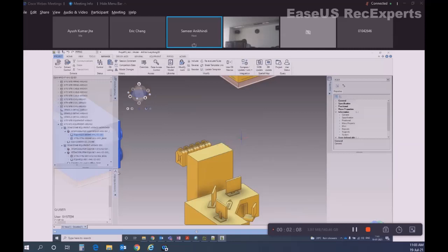Or let us see better with the example of DI, distance command. For example, this locks my northing. DI again. For the first point, I want to use this northing. So I will go to the second text box using tab and press spacebar. So it is locked.